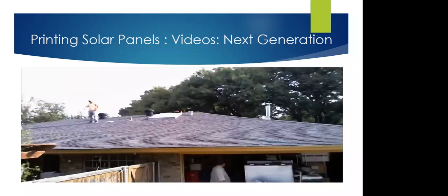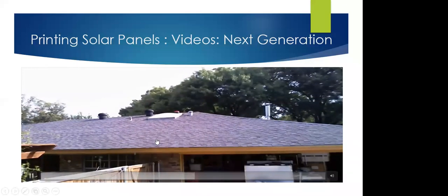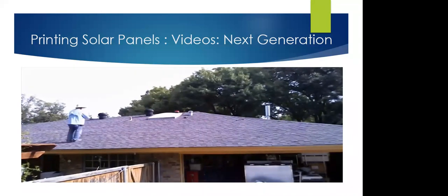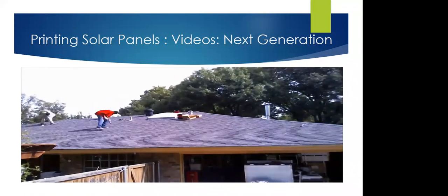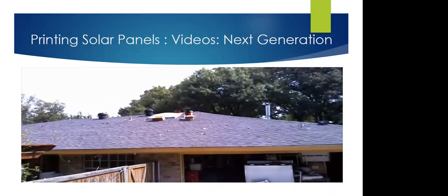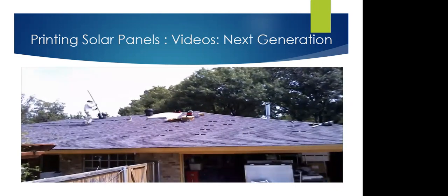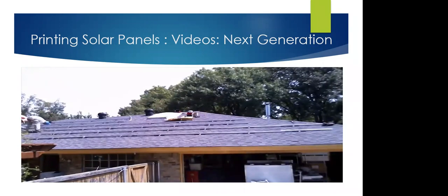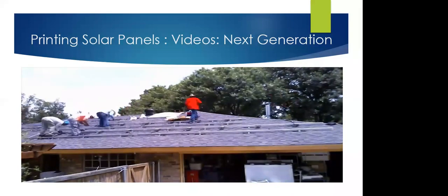Sadly, each technique has its downsides. In slot die printing, for example, the spacing of patterns is hard to control, and gaps reduce the active area of a panel. In gravure printing, contact with the printed substrate can damage the underlying layers. Such drawbacks mean that currently the printed solar cells are less than half as efficient as the best non-printed equivalents. To print thin, pinhole-free layers over more than 1 square meter will require more intelligent, more precise equipment and laser processing techniques.